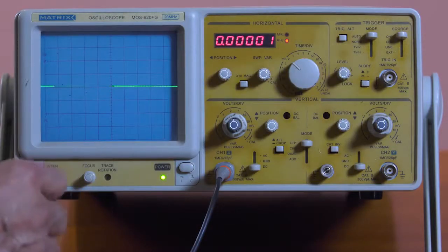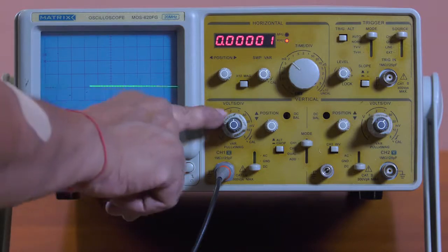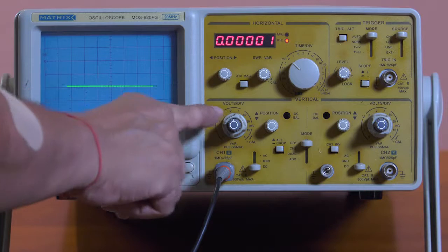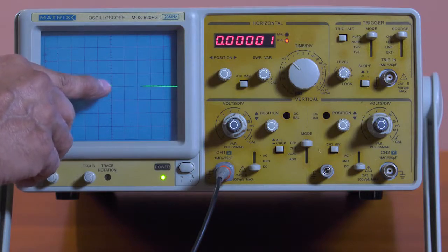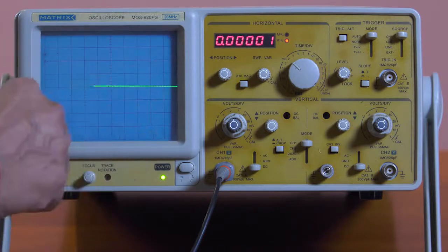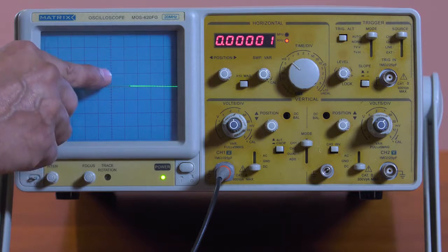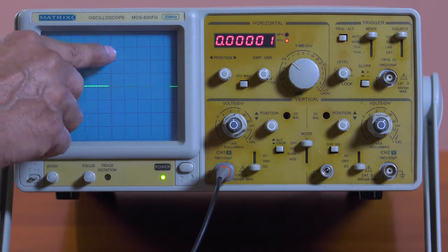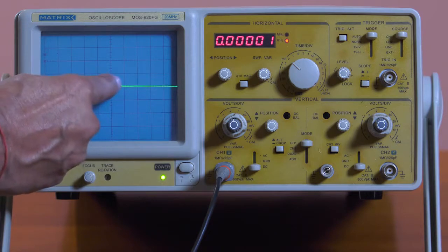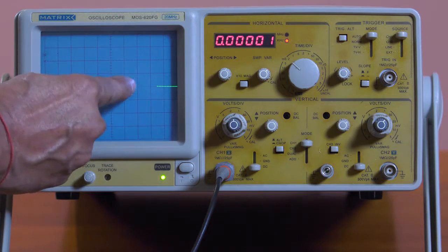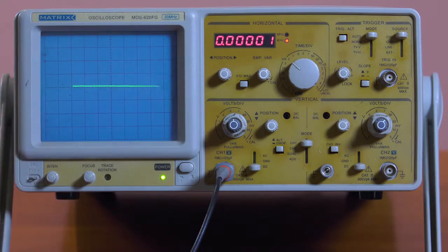Now, the most important thing that we're worried about at the moment is volts per division. Please do not compare or confuse the small lines in between as a division. A division is 1 centimeter. So from the middle, it's exactly like graph paper. From there to there is 1 centimeter, which is 1 division. From there to there is another division, and so forth. And on the horizontal axis, we also have that as a division. From there to there is another division, and from there to there is another division.